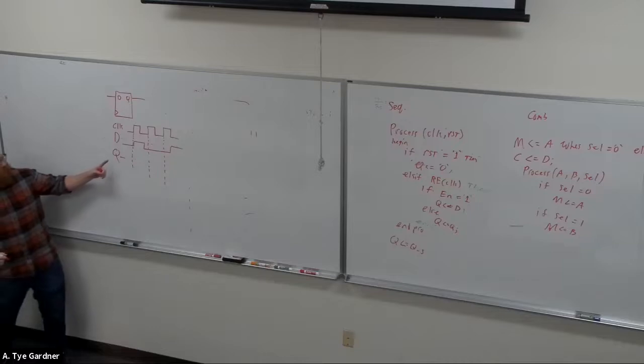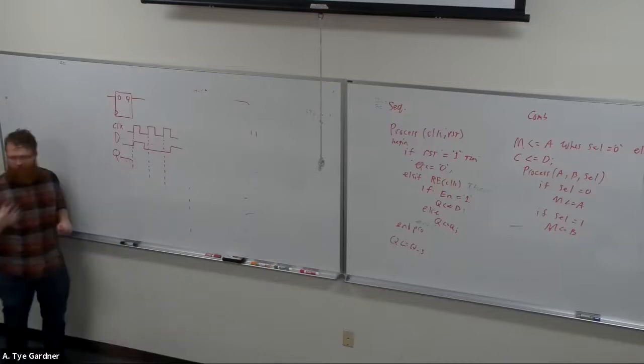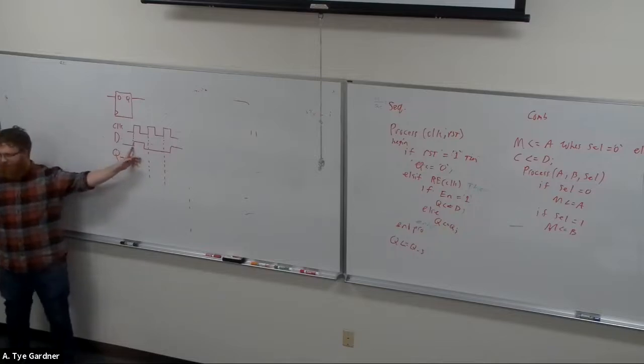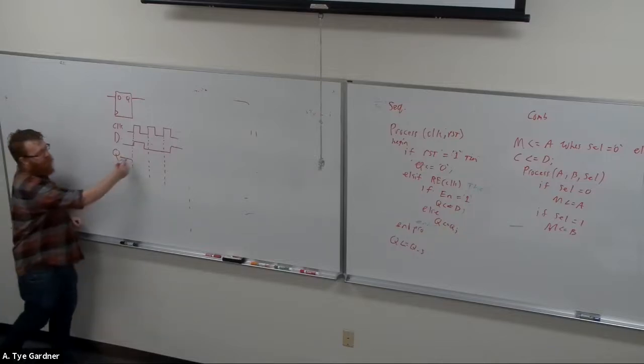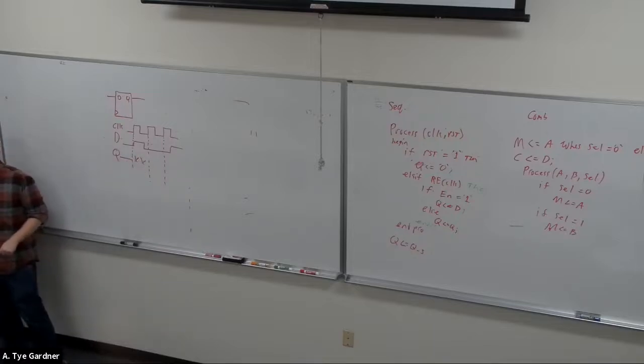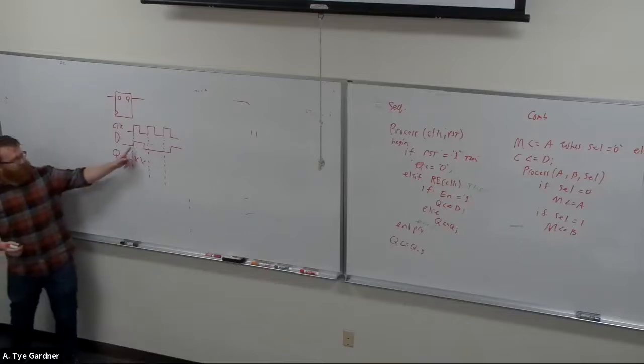And I would go, okay, well, I'm 0 up until here, and then something happens. But almost no matter what my setup and hold times are, this is in violation. So my result is I don't know what that is, right? Are those supposed to be lined up? Not quite. D looks like a little past that. It is, but it's going to violate, right?